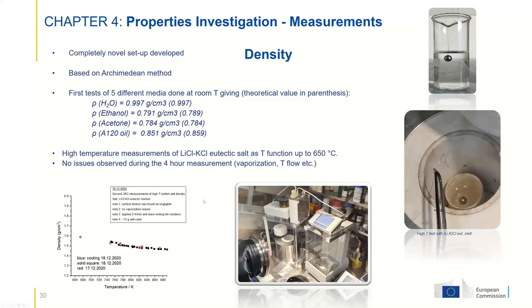So far, we are testing towards high temperature with inactive mixtures, all done in a glove box, again because of the argon atmosphere. You can see it's still a prototype. The principle is based on submerging the nickel bulb into the molten salt and measuring the buoyancy effect, corrected for surface effects of the wire. The results are fairly good. We measured FLiNaK and the lithium chloride-calcium chloride eutectic. Now we measured three compositions of lithium chloride with cerium chloride, as a surrogate for plutonium chloride at a later stage, and got very good and reliable results.